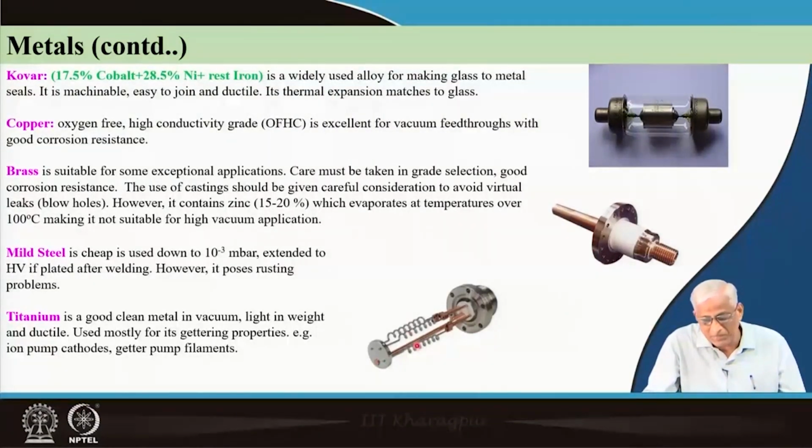These are the titanium filaments, and these are copper feedthroughs with ceramic. So, there is a lot of technology. It is a very costly piece, I am telling you. If a startup comes and they can make a stainless steel flange and attach it to a ceramic and then copper, pass high current, inside a conflat flange with a metal gasket, and you show the customer it will withstand 10 power minus 6 torr, then you can say this will be 2 lakh rupees.